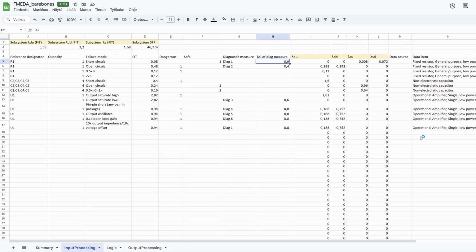In the end, I would also like to mention the effect of the diagnostic coverage on our calculations. Any diagnostic coverage that you claim to be more or equal to 90 will have to have associated failure injection testing or fault injection testing. It is also not best practice to call all diagnostics high diagnostic coverage. In fact, there is a standard clause that will limit your claimed diagnostic coverage, and you should follow these limits when giving any diagnostic measure a DC value.